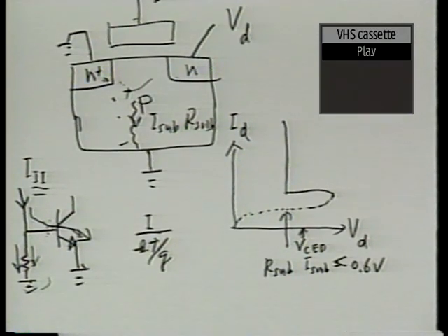Tori, did that answer the original question you wanted to ask about the bipolar transistor? Let me rephrase this and answer it. Tori was asking, now go back to bipolar, not MOS. He happens to know that even if he truly grounds the base terminal and measures the breakdown voltage, it doesn't differ that much. It's a little higher than keeping it open, but not that much higher, not a factor of 3 or 2. So how do you answer that?